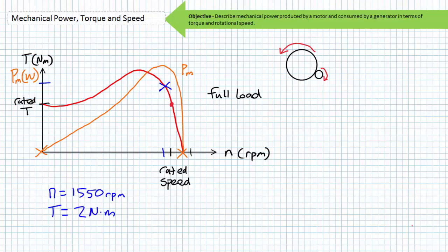Picture a drive gear on an output shaft that spins a driven gear. An example might be a yaw motor on a horizontal axis wind turbine, which actively turns the wind turbine into or away from the wind. The motor is mounted to the nacelle frame, and as the pinion or drive gear on the motor shaft spins, it rotates the frame on an externally or internally toothed slewing bearing, which is fixed to the tower. Another example of this on a wind turbine is the pitch mechanism that changes the angles of the blade using a motor with a pinion gear driving an internally toothed slewing bearing. As the motor spins the pinion, the blade changes the angle of attack.